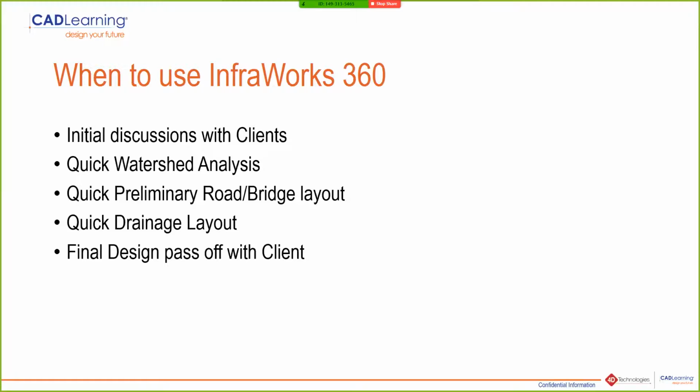Once you're completely done in Civil 3D, if you really want to get beyond preliminary, you've got it into Civil 3D, now you've really got the roads laid out, you've really got the profiles laid out, and you're looking at volumes. Now is the time to talk to the client, make sure this is really what they want. You can take that file from, say, Civil 3D and put it back into InfraWorks 360.